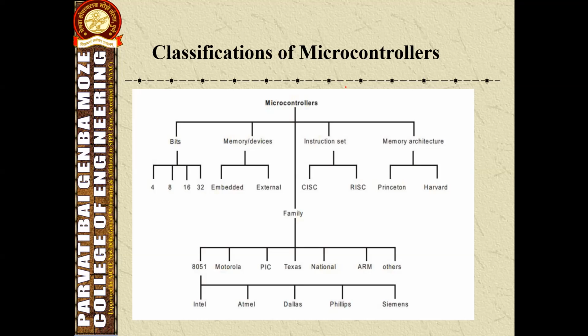The 8031 microcontroller is called the ROM-less 8051. It has the same features and architecture as the 8051 except that it has no ROM, because it has 0 kilobyte of on-chip ROM. Hence, in order to use 8031, we need to add extra ROM to it. The extra ROM holds the program that the 8031 will fetch and execute. The ROM that can be attached to the 8031 can be as large as 64 kilobytes.